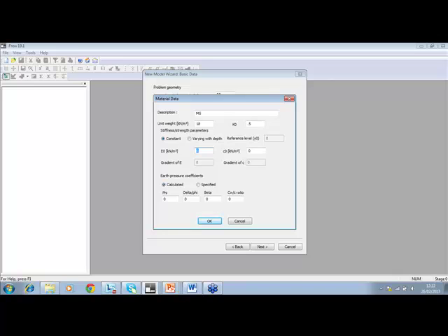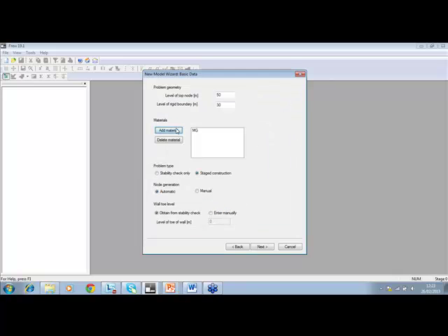We've got a stiffness here of 15,000. It's quite weak, so it's for the Young's modulus. We've got specified earth pressure coefficients of 0.29, 4.5, 1, and 1. Okay, so that's made ground inputted.